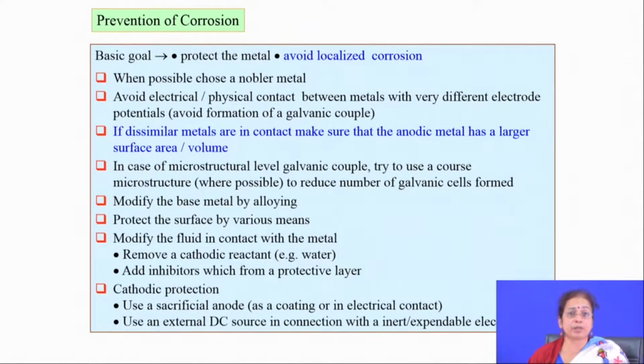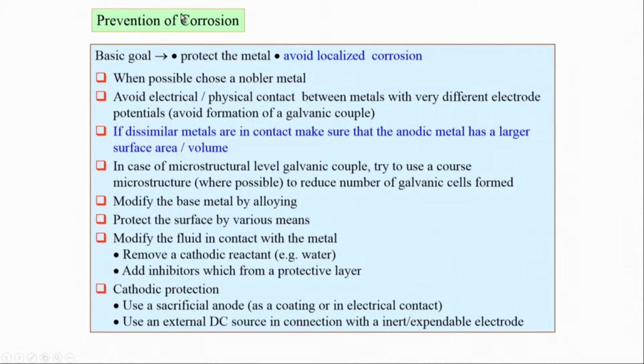In the case of liquid metal corrosion, you can apply a coating, or change the material and use the proper material in that liquid metal environment, or apply a very thin layer of coating which does not participate in the liquid metal embrittlement process. By that process it basically protects the underlying substrate.